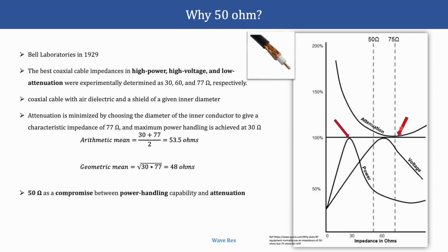and here we can see that in this attenuation curve it is providing the lowest attenuation at around 77 ohm, and when we are considering the power handling capability it can provide the high power handling at around 30 ohm, and when we are considering the voltage handling capacity it is around 60 ohm. So based on these studies they have